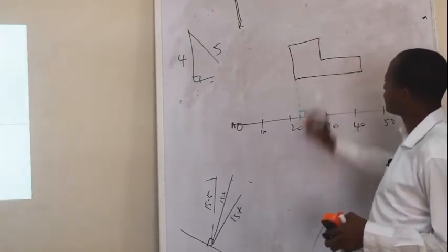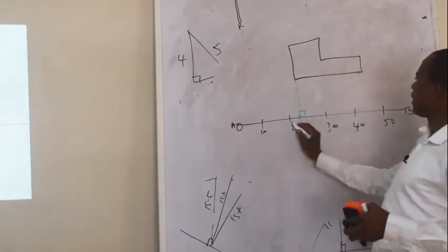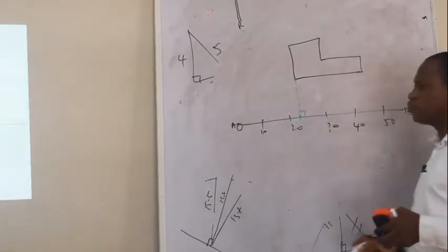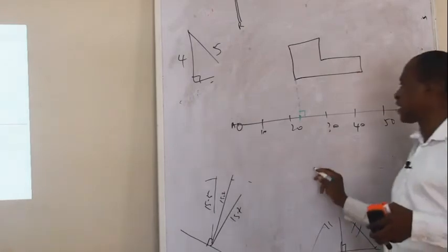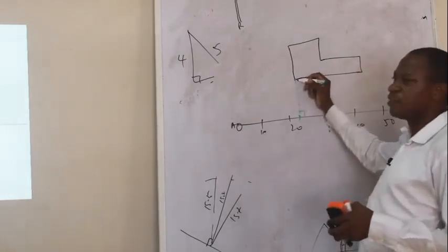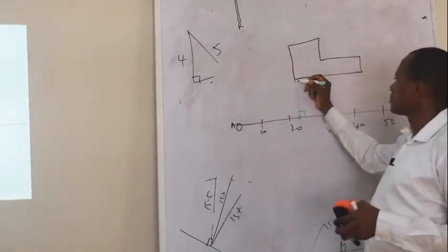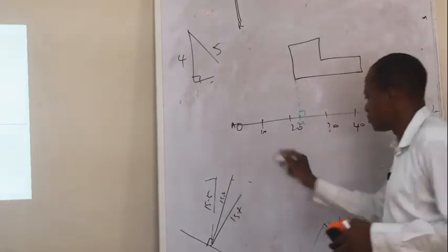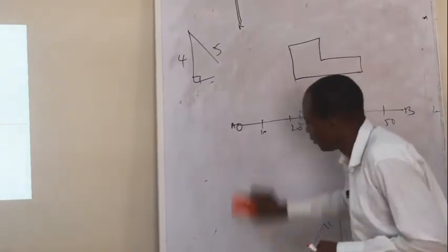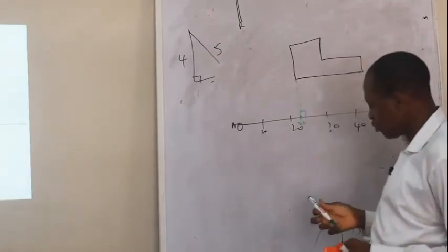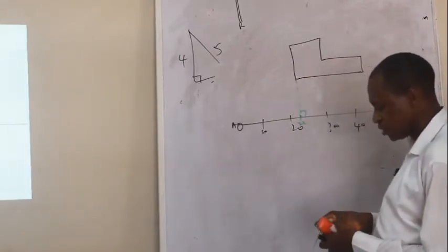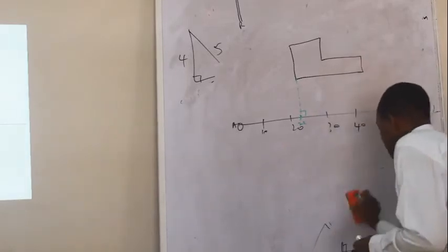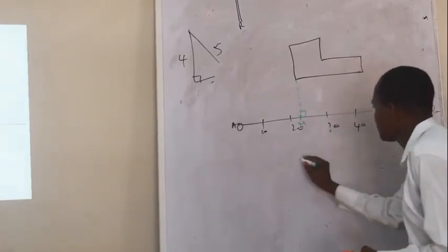So we want to fix this point. This should be around 20, 30, this will be around 22. At 22 means that when you have your field book, you say at 22 meters, I encountered the beginning of a building. And you will fix it at 22. At 22, there's a building. And this is how you normally fix it in our field book.